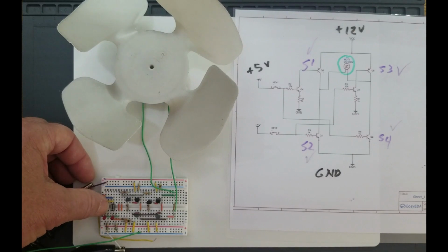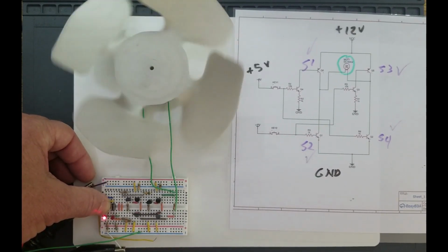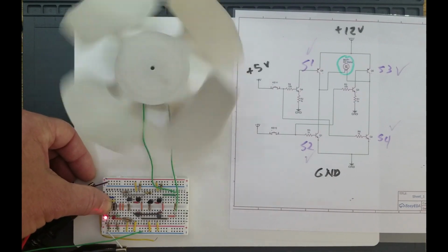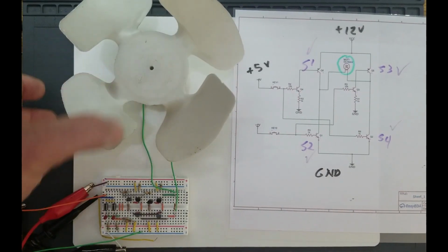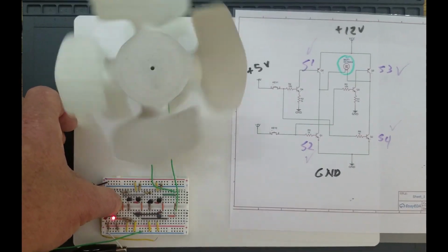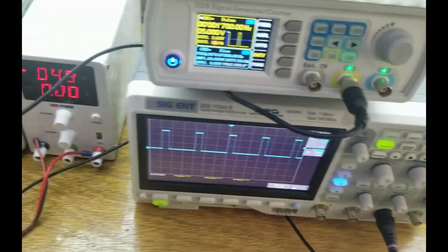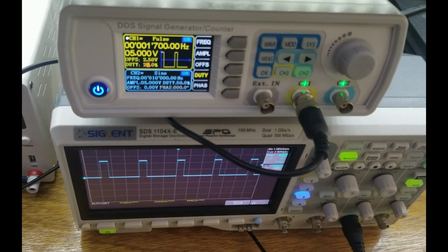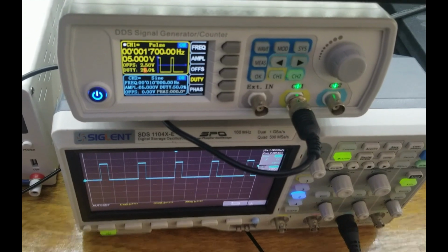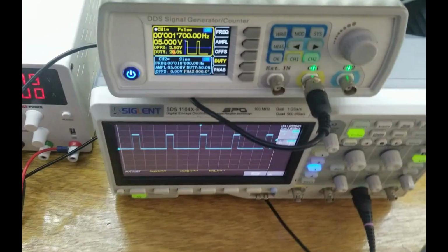So if we wanted the motor to go counterclockwise but to go very slowly, I'm now using a 20% duty cycle to go this direction. I can use that same pulse width modulation to cause it to turn clockwise. So this is a pulse width modulated signal right here. It's a 20% duty cycle. And that's the resulting speed of the motor.